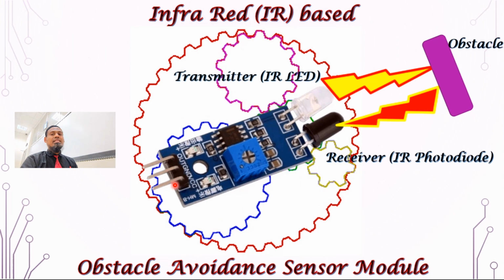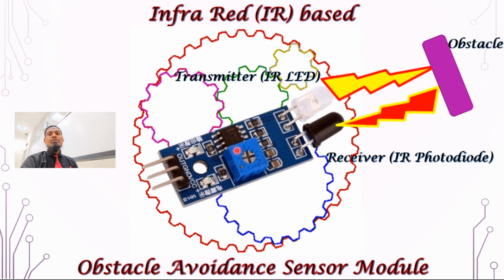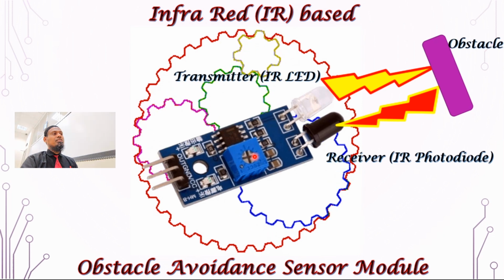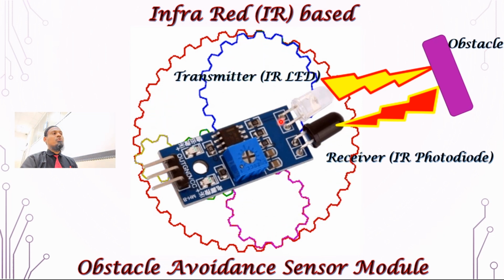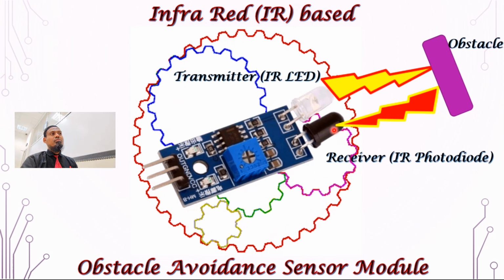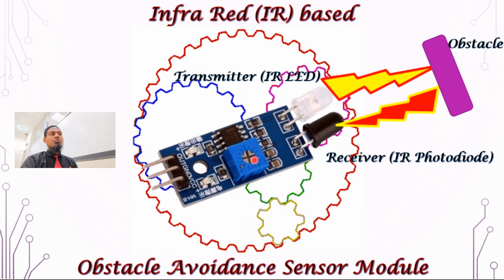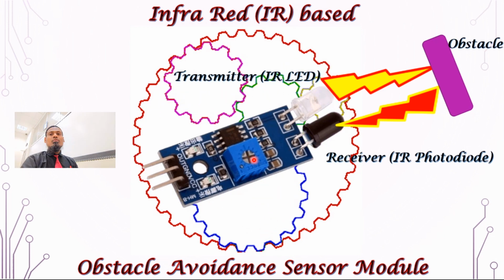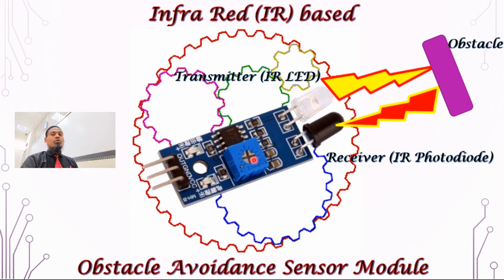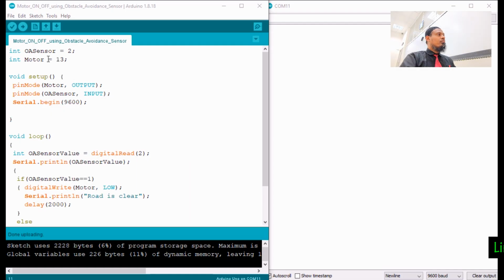With the output pin, there will be VCC and ground pins in the module, and you will be provided with a potentiometer. The usage of this potentiometer is to tune the distance to be covered by this module. You can increase or decrease the visibility of this module by tuning this potentiometer. Now we will discuss the Arduino coding for using this module to control a DC motor. This is the program which we are going to use for controlling the electric motor.